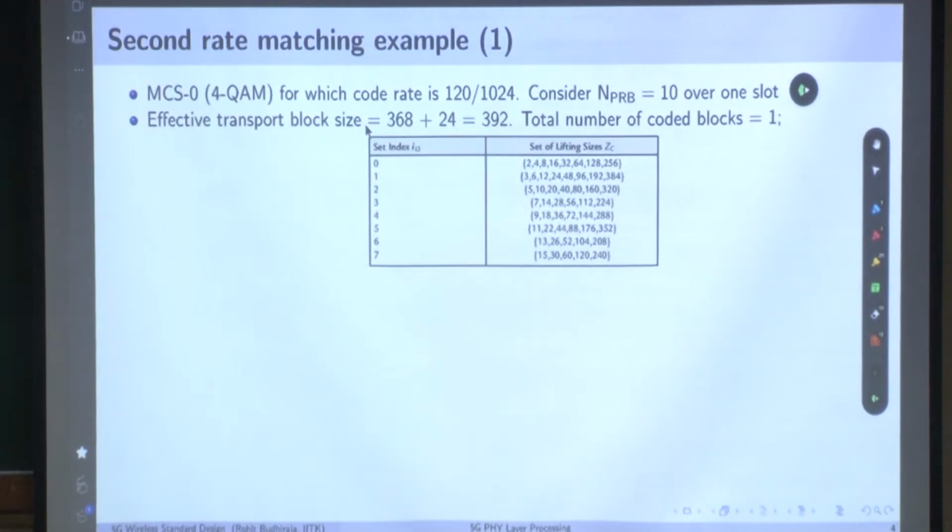If this length doesn't match what the LDPC encoder can encode, what needs to be done? One needs to append filler bits. So the segmentation module, even though it's not going to segment, is going to append those filler bits. So the segmentation module has its role of appending the filler bits.